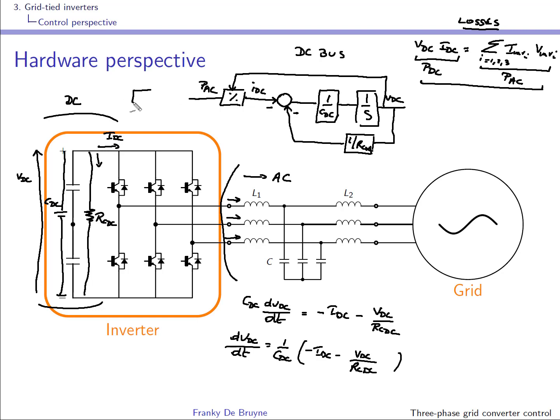Here I need the power on the AC side, and it's simply obtained by taking the scalar product of V inf and I inf, or the product. This is going to be a product, so the output will still be a vector, and if I sum this, I have actually constructed the scalar product.